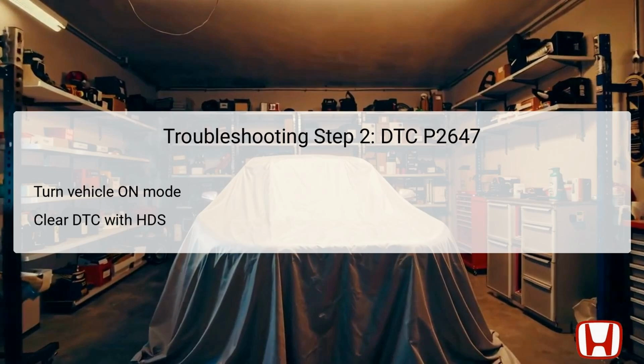Clearing the DTC helps in resetting the vehicle's monitoring system and allows you to check if the issue is intermittent or has returned. Following this, selecting the VTEC test in the HDS inspection menu is essential. The test will validate if the sensor is functioning properly. An OK result indicates that the system is operational at that moment, suggesting an intermittent fault may be present. Recording any freeze data can guide further analysis if issues arise again.